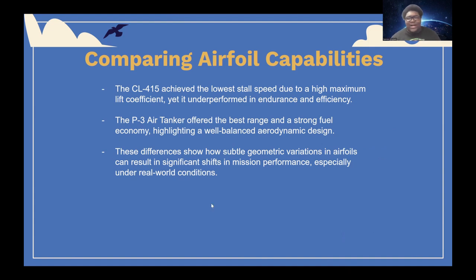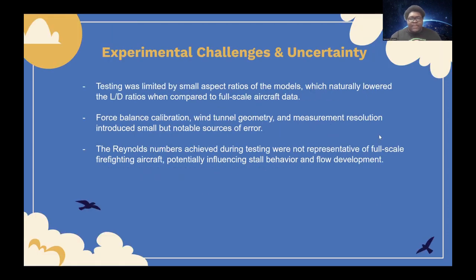These differences show how subtle geometric variations in airfoils can result in significant shifts in mission performance, especially under real-world conditions. For experimental challenges and uncertainty, testing was limited by small aspect ratios of the models, which naturally lowered the L/D ratios when compared to full-scale aircraft data.